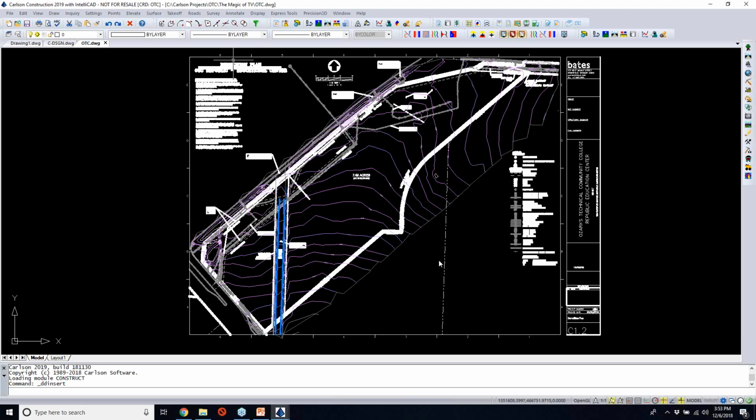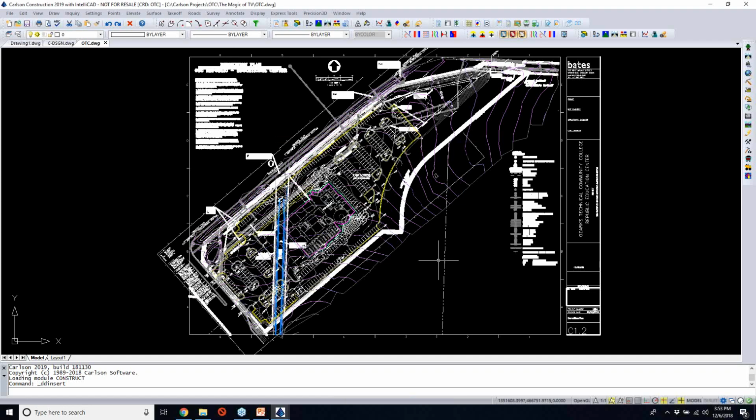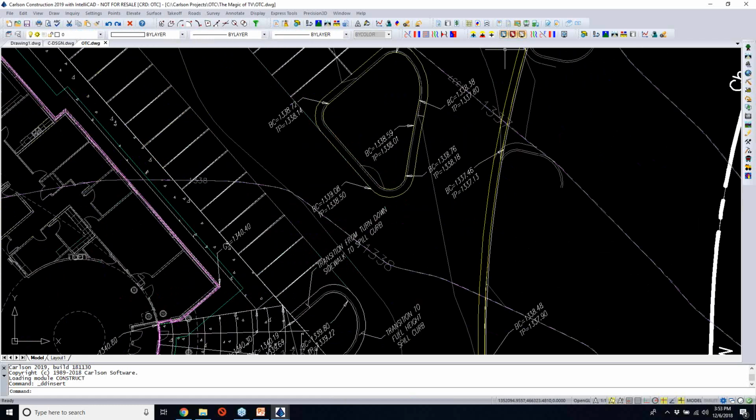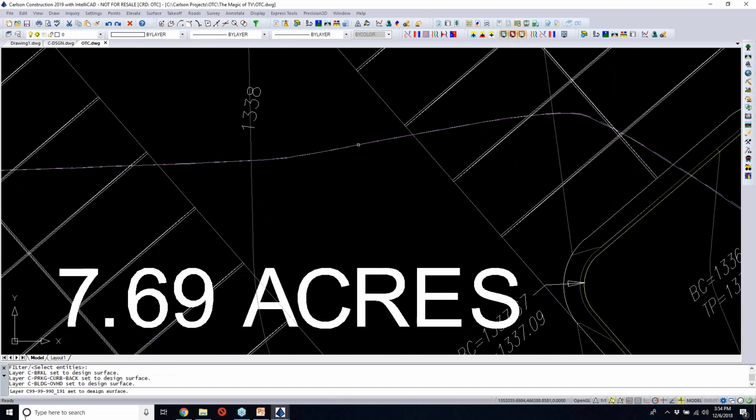And then the other thing that's sort of nice is that as additional changes need to be made, there we go. We can adjust any kind of values for subgrade adjustments and things like that. So now we've got what was just the design that was being brought in, and we can now start to say, okay, let's indicate items. So underneath my set layer for design, I can say, well, that layer is a design, maybe this layer is a design, that layer is a design, any of these contours in here are going to pick up for design. And so I can start to visually pick them up if I want to, or if I have things that are properly structured in terms of the layering scheme.